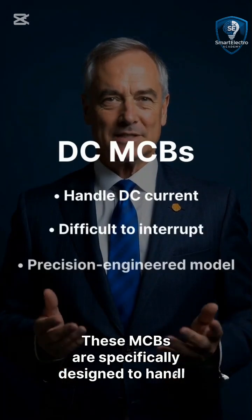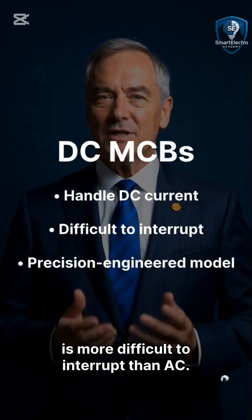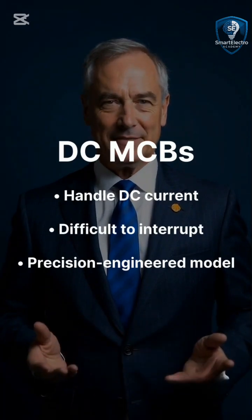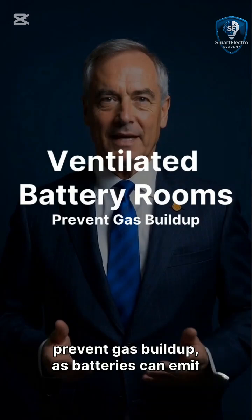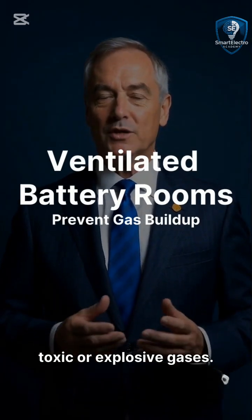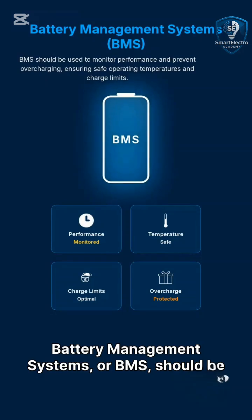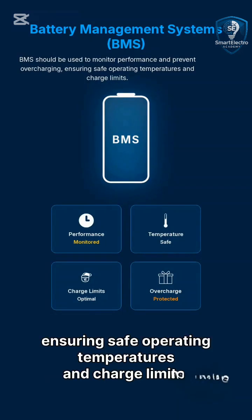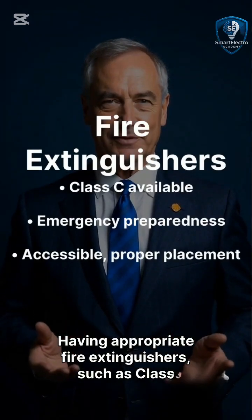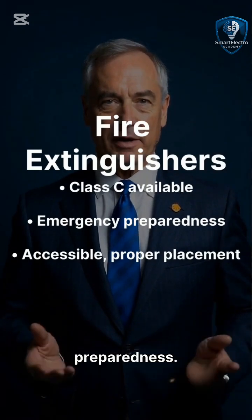These MCBs are specifically designed to handle the unique characteristics of DC current, which is more difficult to interrupt than AC. Properly ventilated battery rooms are necessary to prevent gas buildup, as batteries can emit toxic or explosive gases. Battery management systems, or BMS, should be used to monitor performance and prevent overcharging, ensuring safe operating temperatures and charge limits. Having appropriate fire extinguishers, such as Class C, readily available is vital for emergency preparedness.